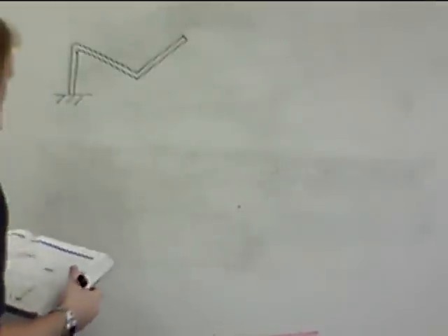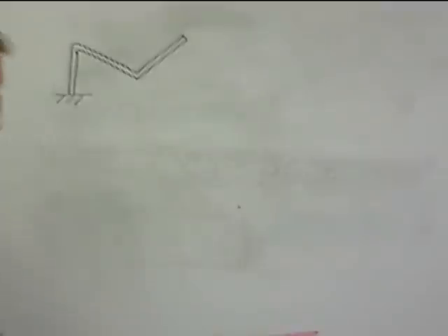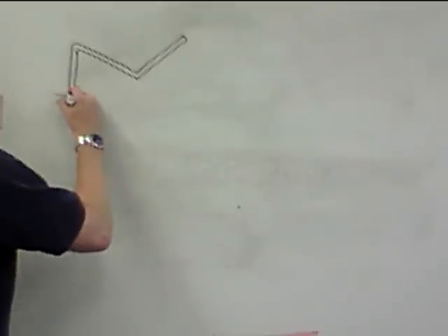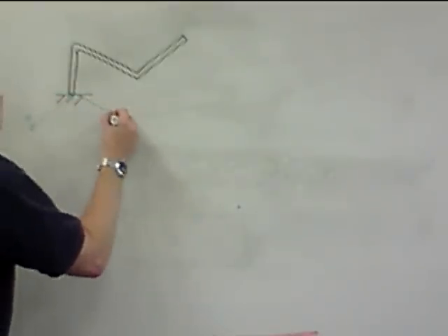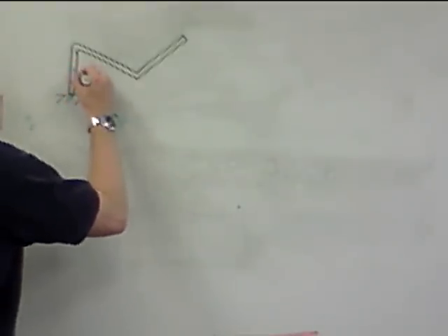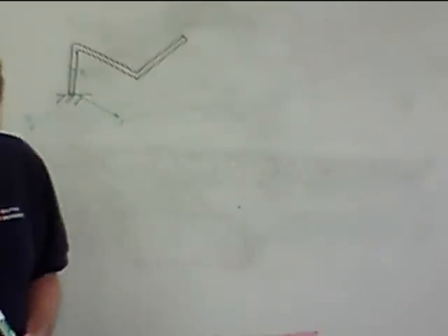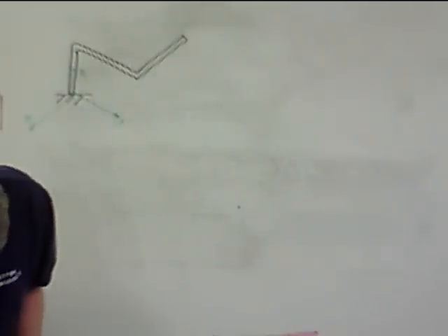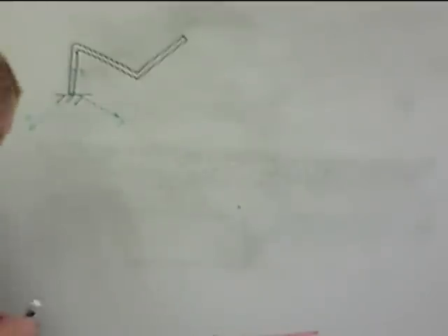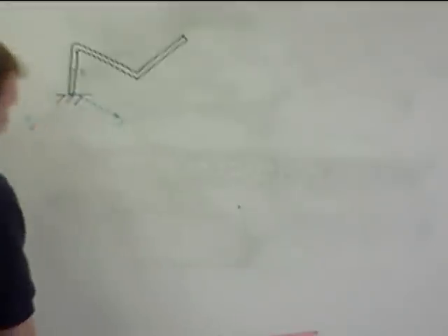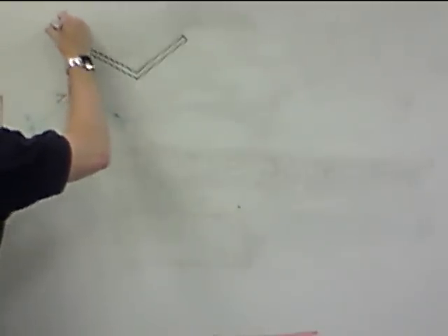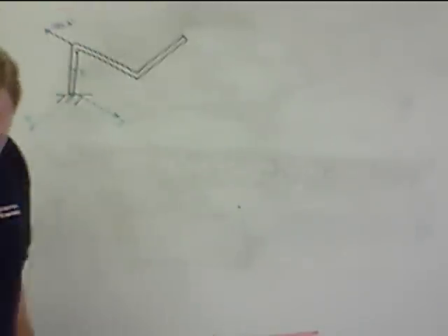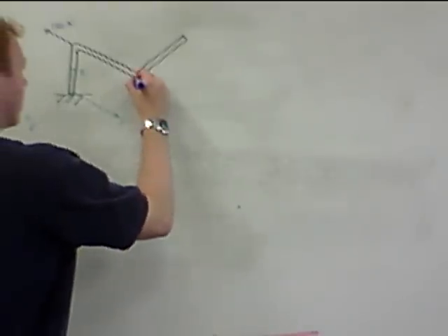In terms of coordinate axes, I'll do my best here. This is the origin. We're going to have x in this direction, y in this direction, z in this direction. We're only going to have three forces acting on this. We're going to have a 100 Newton force going directly off the back, in the negative y direction. And in the negative z direction, a 200 Newton force acting at this joint.